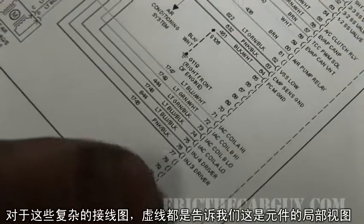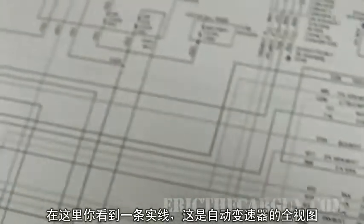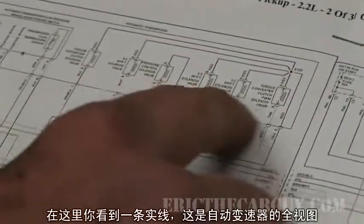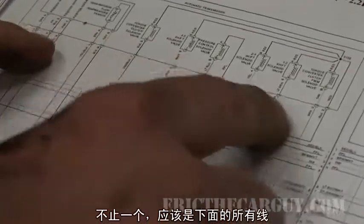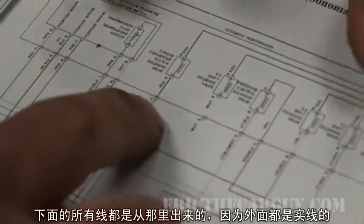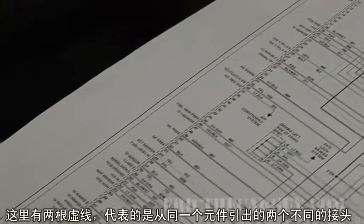One of the things with these Mitchell diagrams is the dotted line always shows you a partial view of that component. So you see the dotted line around the computer, that's not a full view of it. The full view was both halves put together. As a comparison, if you look at the automatic transmission, you see a solid line. That is the complete view of the automatic transmission, so all the wires coming out of it are here, because everything is solid around the outside, as opposed to the dotted line at the computer. Over here you've got 2 dotted lines, representing 2 different connectors going into the same component.